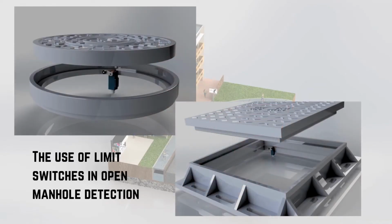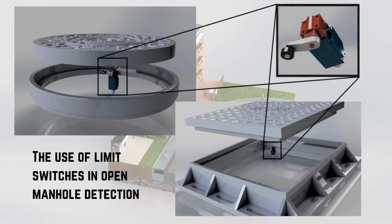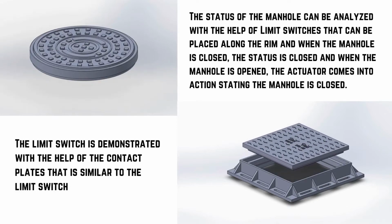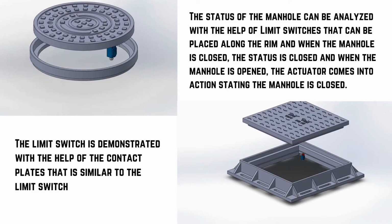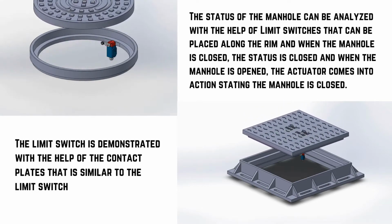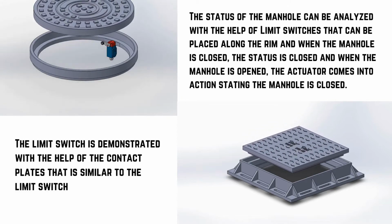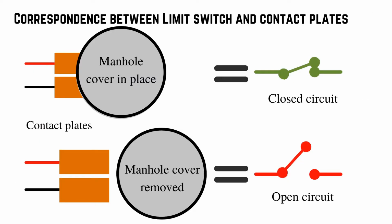Open manhole detection with LED signboard. The status of the manholes can be evaluated using limit switches positioned along the rim. The common terminal of the switch is connected to a positive voltage while the normally open terminal is connected to the ground. As a result, when the manhole lid is closed, the switch is pushed or is in the closed position, sending a high signal to the controller. We can determine if the manholes are open or closed by analyzing the signals received from the switches.